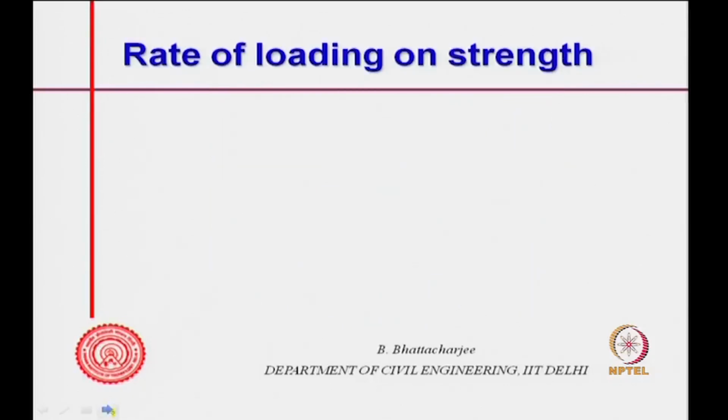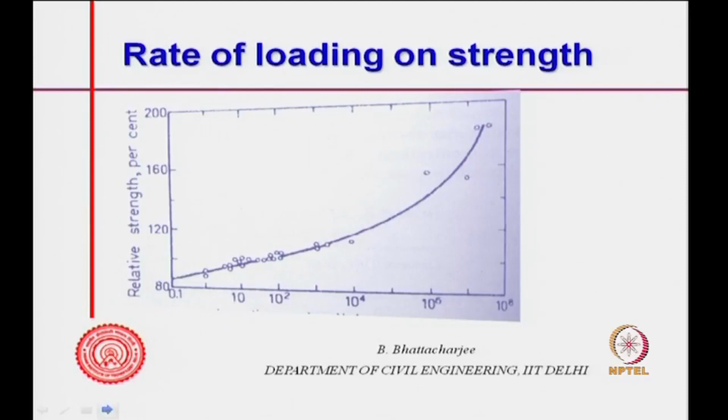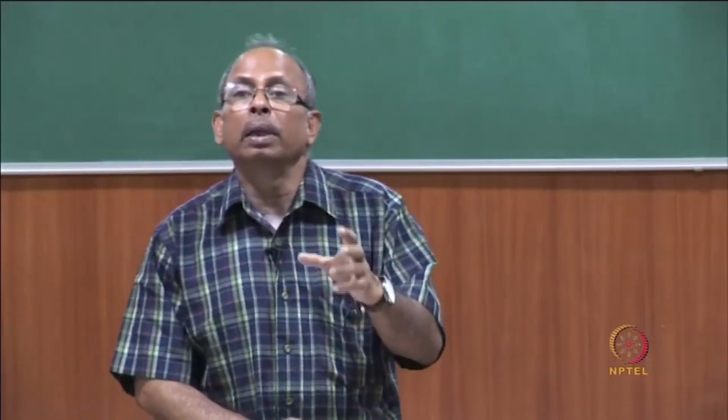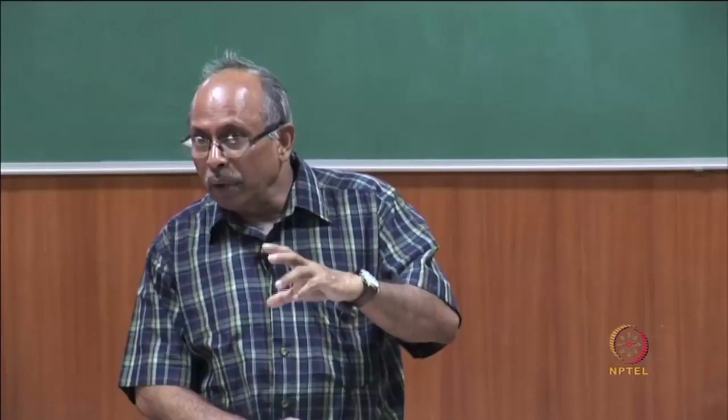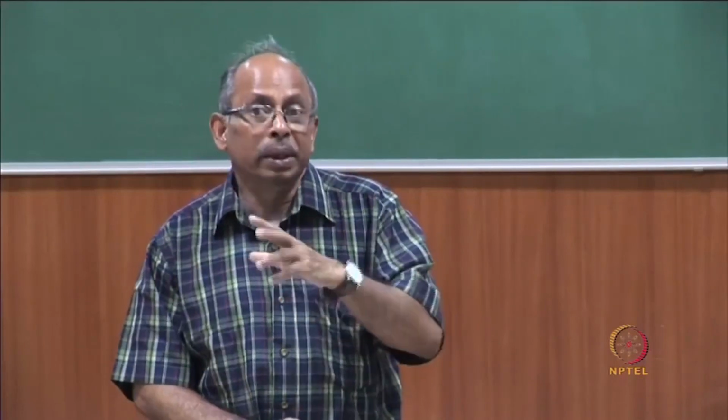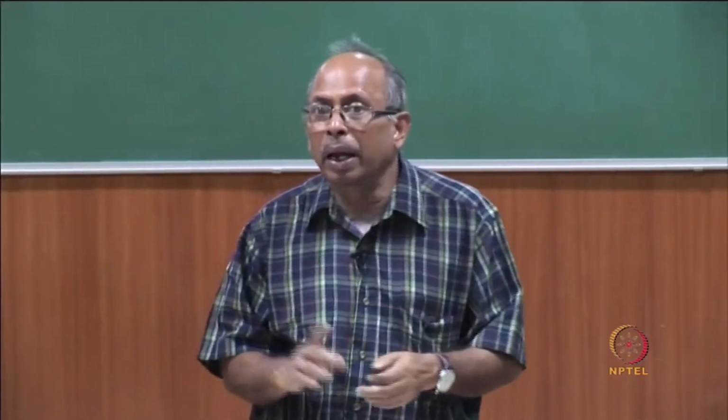Similarly, if you see relative measures, with a higher rate of loading, load applied per second, the relative strength increases. So, at a higher rate of loading, whether it is a strain-controlled situation or you are controlling the rate of load application, because they are not the same thing, load control and strain control are different.